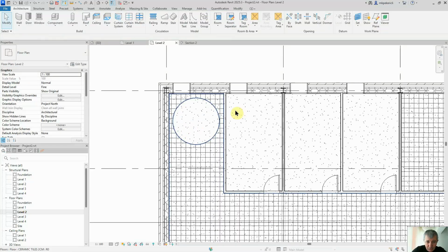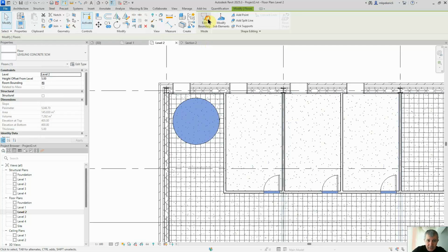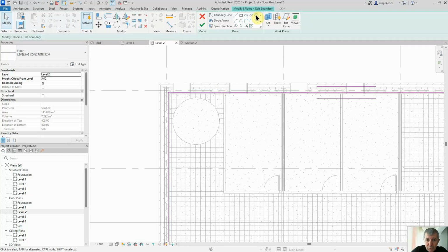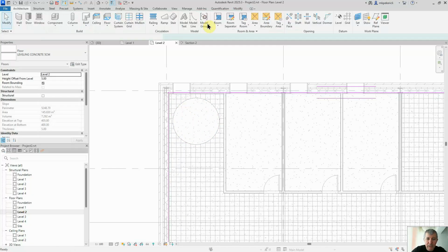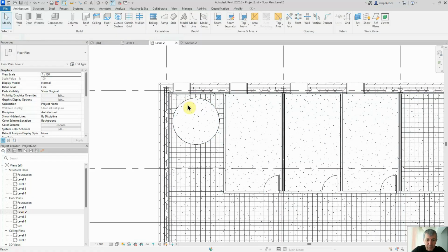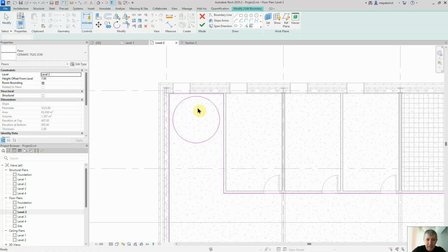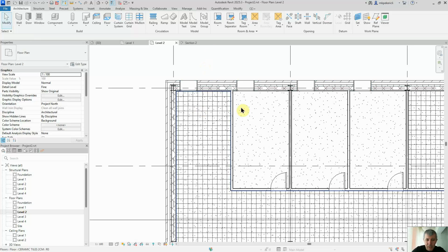So I'll click on this floor, and I'll make another opening. Select elements by face. Yeah, let's select this one. Edit boundary, and we'll create another round opening. But can we make sure that they are aligned? This one? No, it's not. I mean, it's not very easy. You know what? I have another idea. This way we'll be learning another new thing. Let's get rid of this opening that we did. Okay, this is perfect.